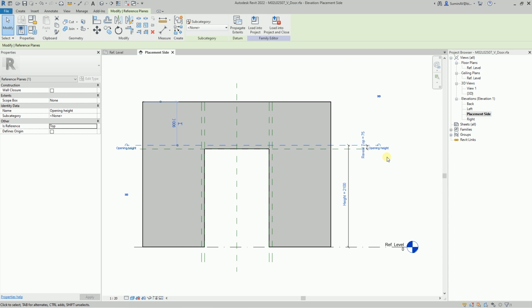Besides the name, a void circle symbol appears at the ends of the selected plane. Using this circle, you can change the plane length. Another controlling symbol is the 3D icon. When it is on, and by default it is always on, and the length of the plane changes, its display also changes in all views in the file. That is, now we will see the altered length if we move to other elevation views, where this plane is also projected into a line.